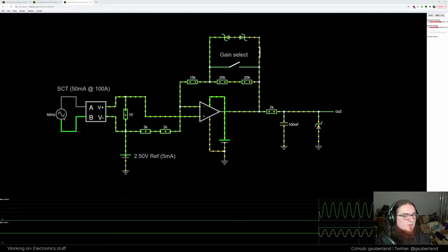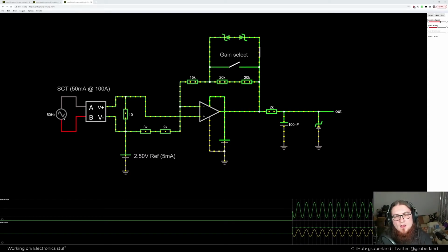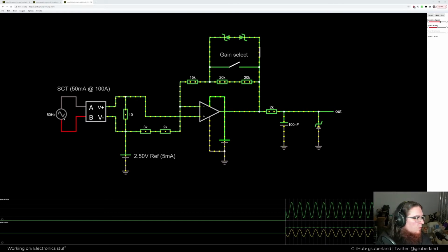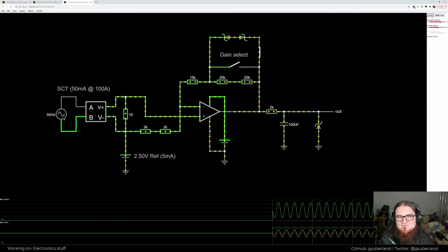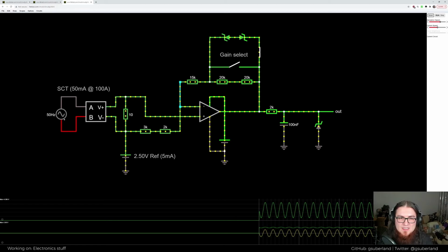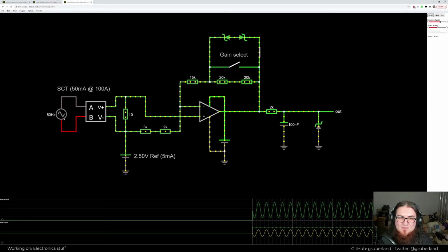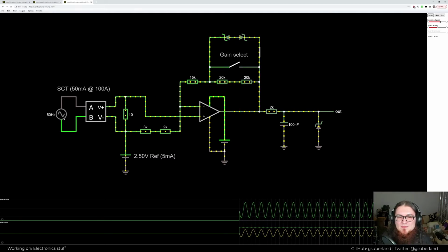4.406. And I'm looking over at my screen on the left here because I've got the calculations over here. And if we then go and take a look at what that is in percent, that brings us down to around 1.8% error, which is acceptable. Now, we could lower these resistances even further, but we're really starting to tax this voltage reference.